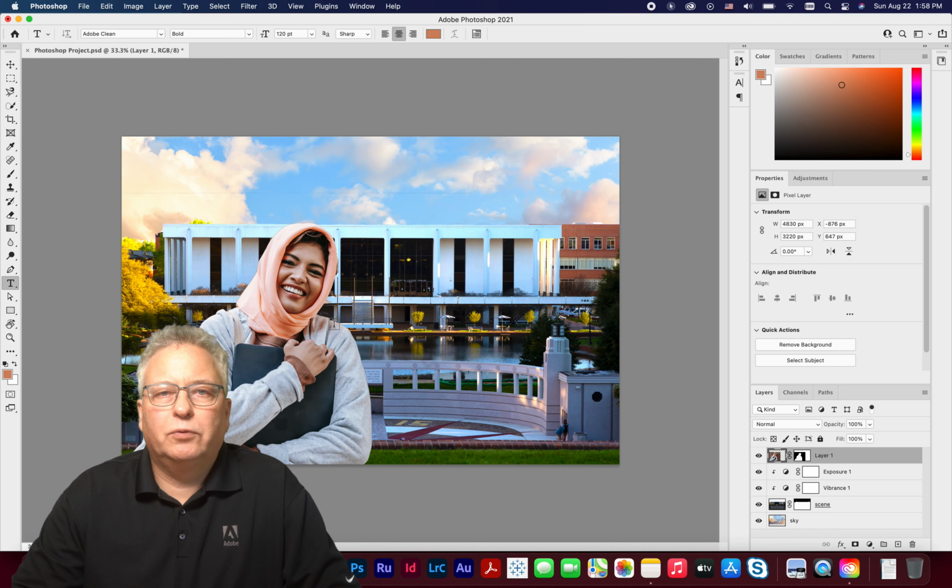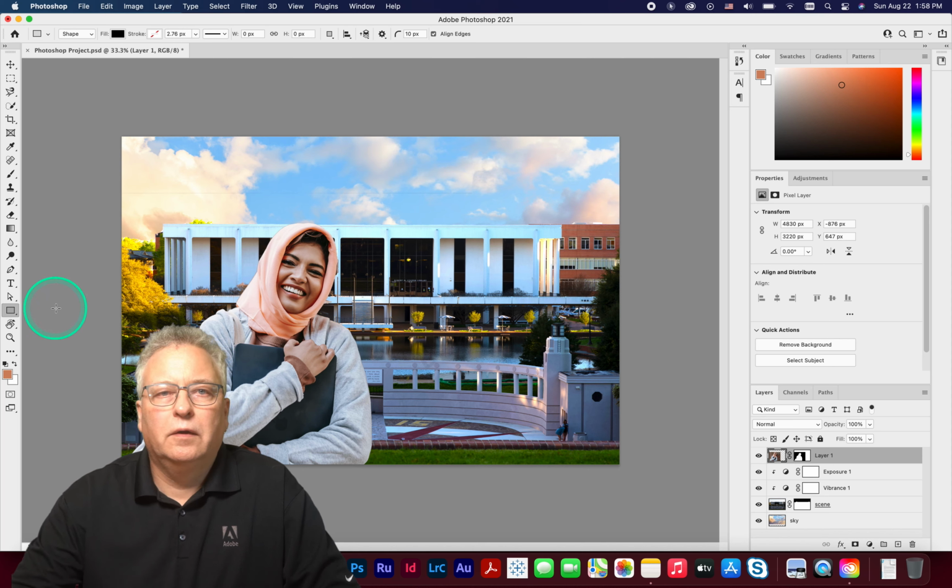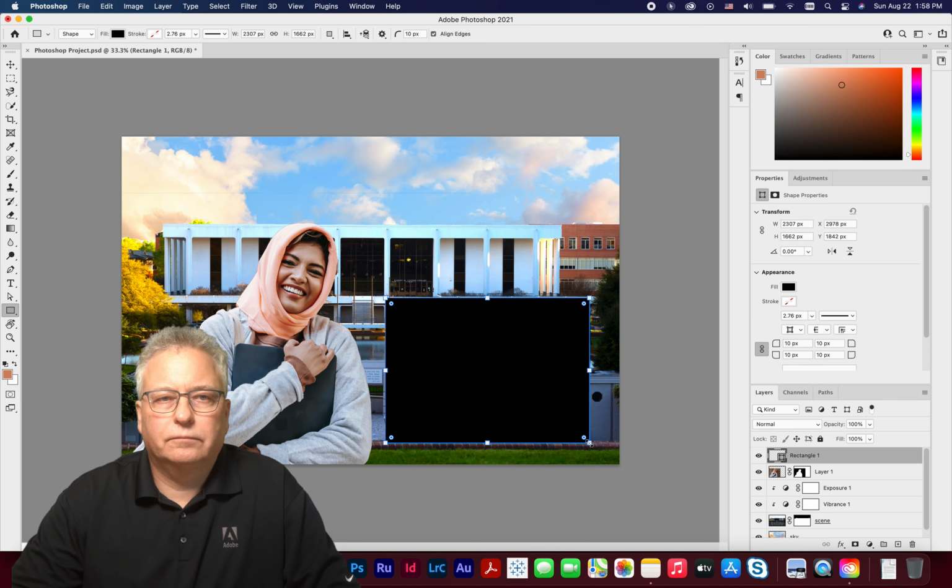Click and hold the Shape Tools button in the Photoshop toolbar and choose the Rectangle tool. Place the cursor in a document window and drag down and to the right to draw a simple rectangle. Click on either of the small circles inside the rectangle corners and drag inward to convert to rounded corners if desired.